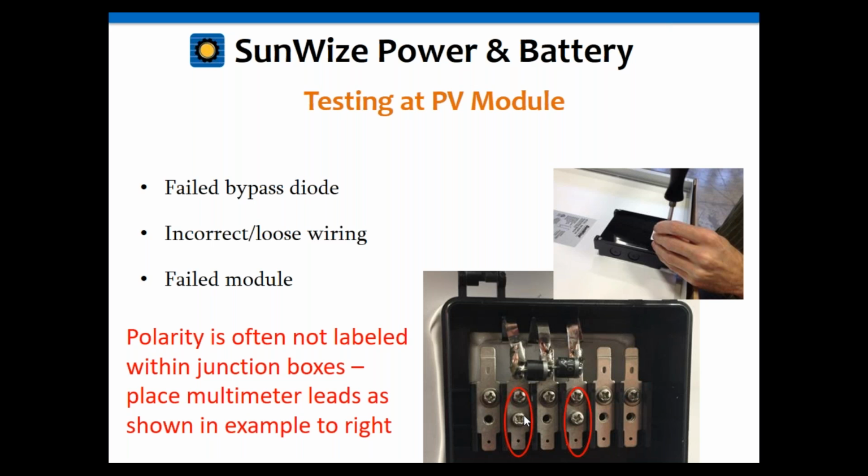There's a delta sometimes as much as 40 or 50 degrees between daytime and nighttime temperatures. And over time, all that expanding and contracting can cause those screws to loosen up just a little bit. A little bit here, a little bit there, it starts to add up. And next thing you know, 5 years later, what was tight is now loose.